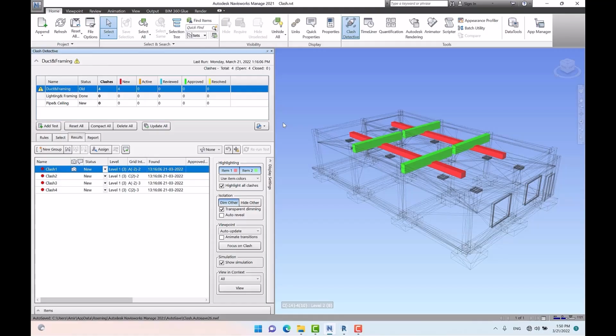Thenceforth, you can analyze and observe the entire clash in your test all together. And actually, at the final session, I'm gonna review all of these topics, especially the clash detection test and the colors. If we use highlight all clashes, it helps us to distinguish the density of the clashes in the whole project, or to recognize the places in the project in which more clashes are found.